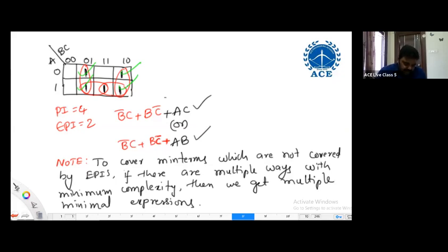One example I mentioned, Rajendra Kulkarni. Fan out depends on the logic family. If you come to the unipolar logic family, there won't be any current. Ideally we say that CMOS fan out is infinite, but there are some issues while calculating propagation delay. If you keep adding logic gates at the output side, the gate capacitance of each and every MOSFET gets added as load capacitance for this logic gate.